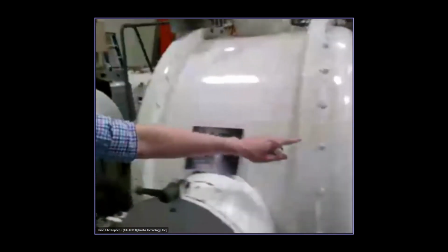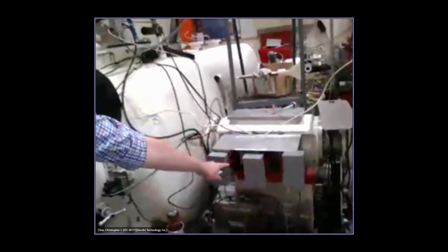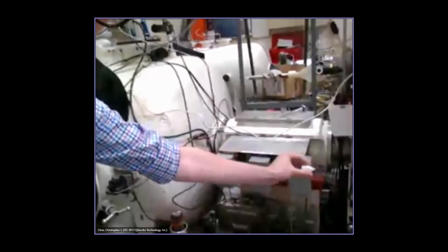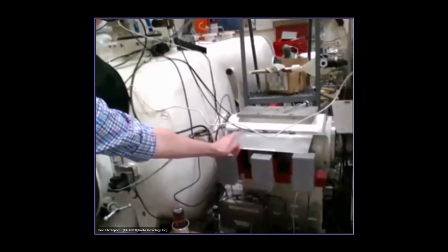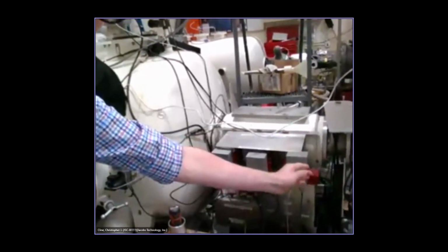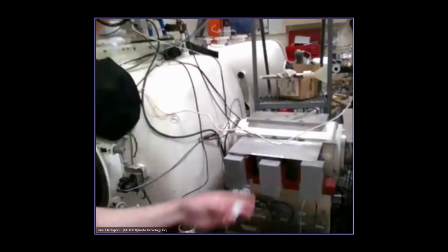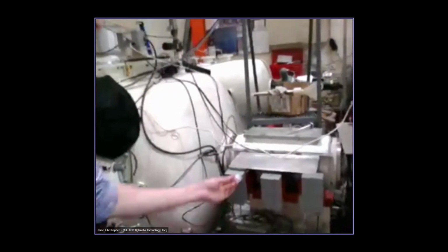As soon as it leaves this barrel, it's in free flight, flying through here, and then we have a series of lasers. These lasers have a known distance between them. The projectile will occult those lasers in series, and since we know the distance and we know the time that it breaks all of these lasers, we have multiple measurements of how fast this is going, and that's how we determine what pressure the sample reaches.